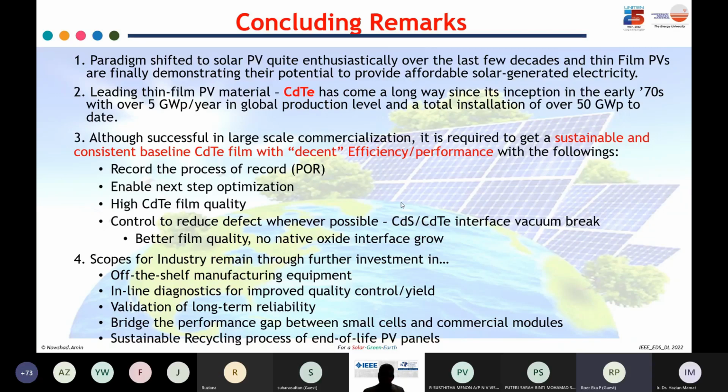And cadmium telluride is not only a solar cell material, but also an X-ray detection material. It could be used for some kinds of sensors, like different kinds of UV sensors. And also, apart from being used in nickel cadmium batteries, it can be used in other things. And also end of life research. That means after 20 or 25 years of lifetime of this kind of solar panel, what to do with the solar panels? We can do research on how to efficiently collect back that cadmium telluride and recycle it, reuse it for the next batch of solar panels with better configurations.